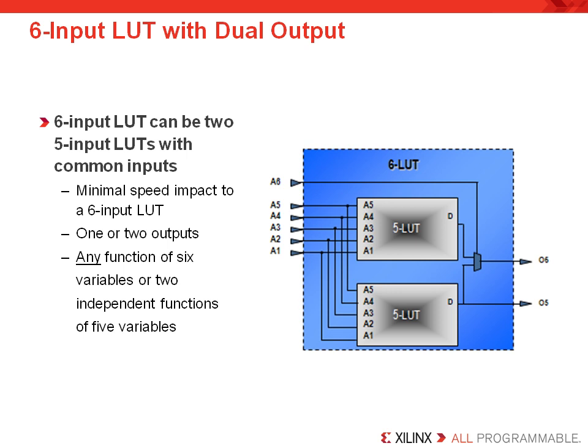Every customer must understand the input limiting nature of LUTs because many customers are used to building with ASICs. It is important to understand that the HDL code you write needs to be optimal for the FPGA. This is because ASICs are faster than FPGAs, and it's much easier to get good speed from an ASIC with suboptimal HDL coding styles. This is highlighted when you consider what you would get if your combinatorial logic had 7 inputs. Because the LUT has 6 inputs, your synthesis tool would be required to add a second LUT in series with the first. This would then dramatically increase the delay associated with this path and cut the maximum frequency possible.